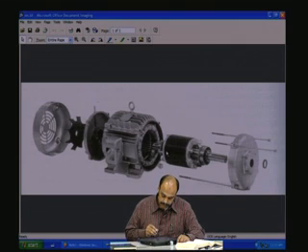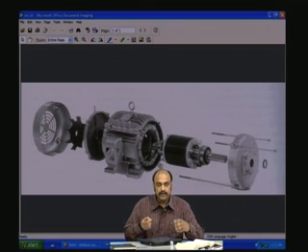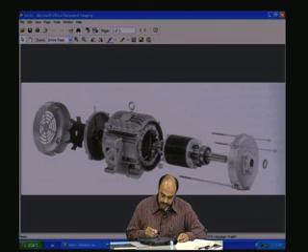Then inside here you see some coils or windings, and those are the stator windings, which form the various poles, the A phase poles, the B phase poles, the C phase poles, and so on, wound on the circumference of this stationary system, and that is called the stator. This is the yoke, and the stator is anchored onto the ground through these foot plates, and it doesn't move.